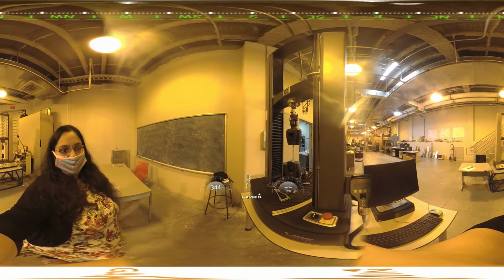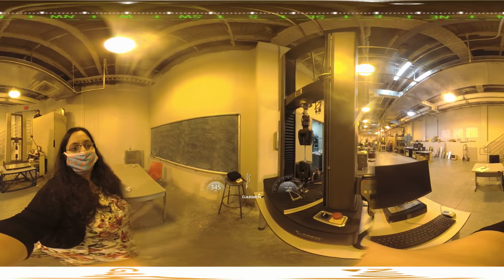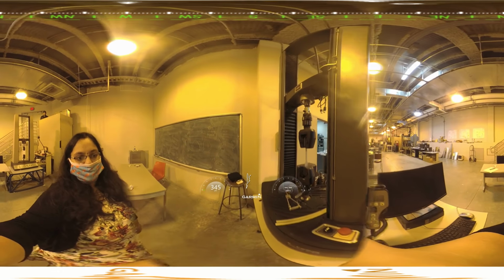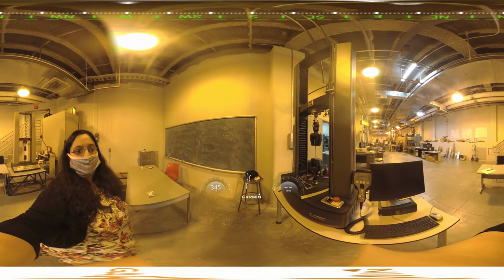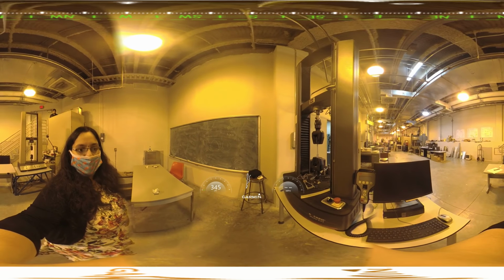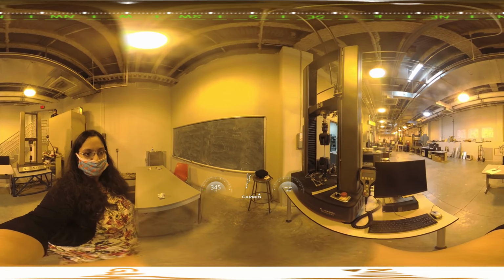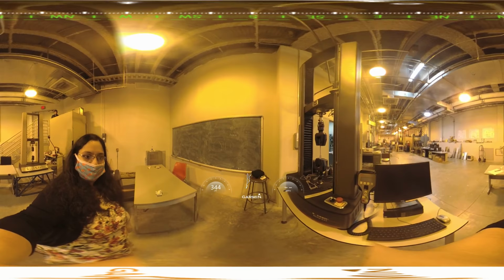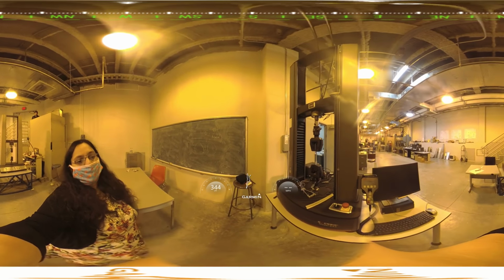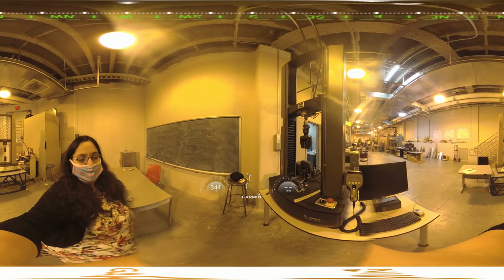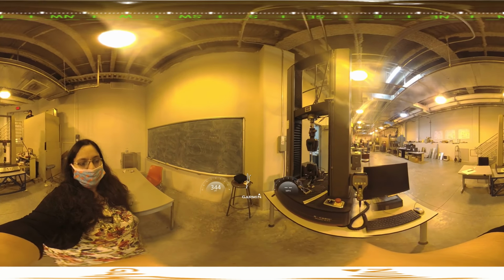We supply a constant strain so that the specimen is pulled on both the ends, and we observe how the stress varies as we change the strain. This will help us to get the stress strain curve and calculate the Young's modulus, the ultimate tensile strength, the fracture strength, and the yield strength.